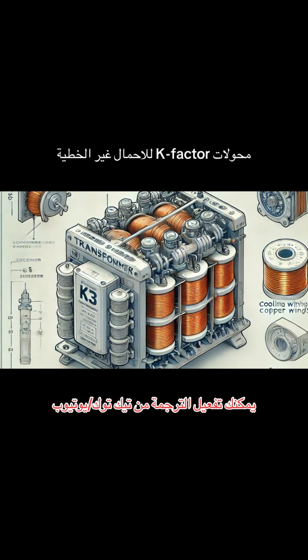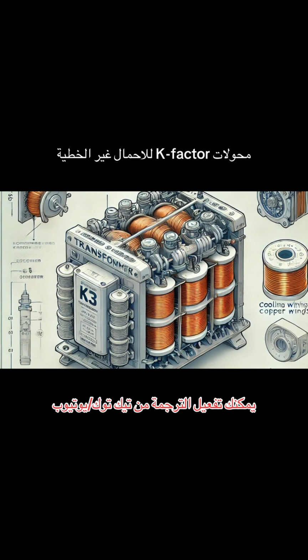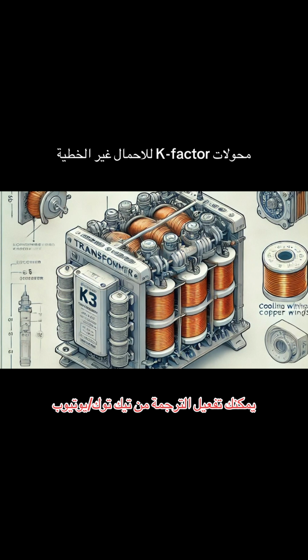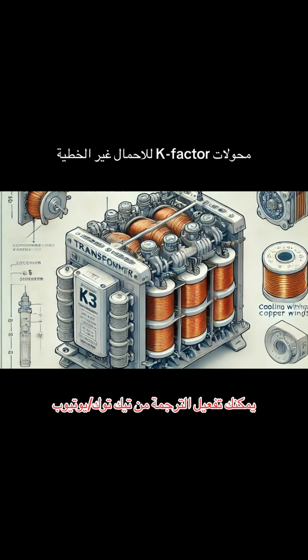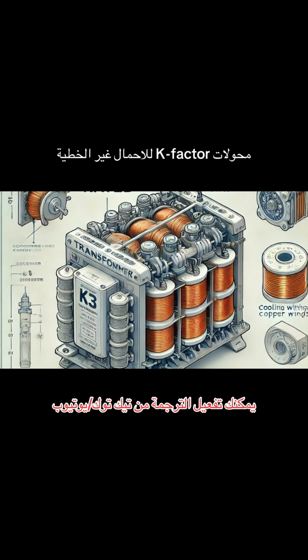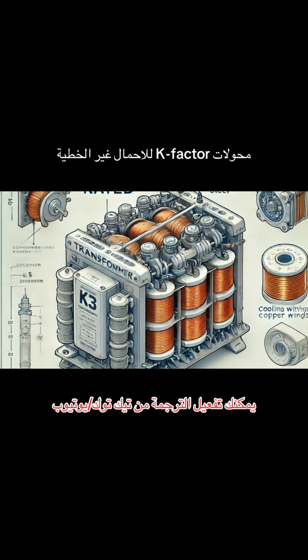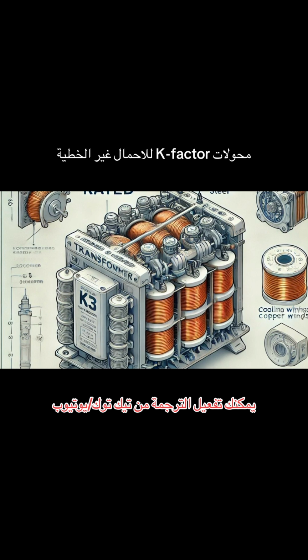And that brings us to the solution that the paper highlights. K-factor transformers. These aren't your everyday transformers. They're specifically designed to handle this whole harmonic overload issue. Okay, so what's so special about these K-factor transformers? What's different about them that allows them to cope with all this extra harmonic current?